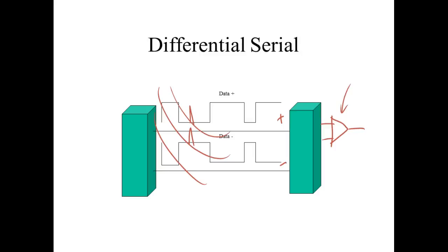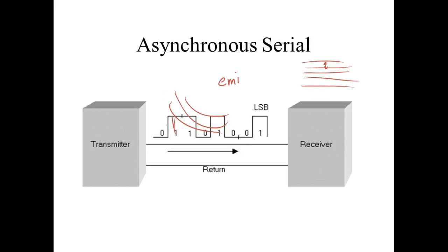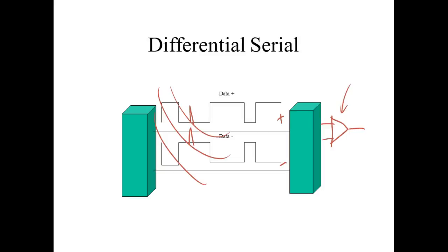Serial ATA. Differential interface. So now we refer to this as single-ended. So if you ever hear single-ended, that means it's a data wire plus a ground. Differential means we don't use ground, but we always have a difference of potential, right? So to recognize voltages, we have to have a difference of potential, and we always have one, because when this one's high, this one is low, and when this one is low, this one right here is high. So we always have a current path. It's just that we don't use ground anymore, and we use differential amplifiers. Beautiful interface.